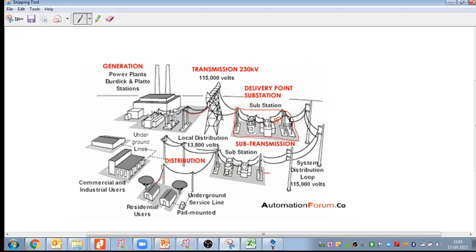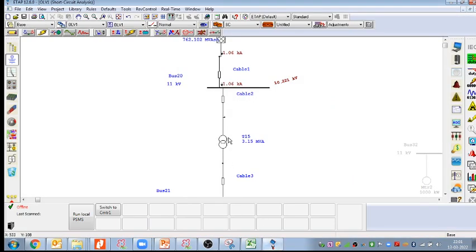Second case that I am taking, if the fault is at this side, then how much fault is fed by these locations to this substation, that we can say remote-in fault. Both are the same, we are telling as the through fault. This is example number one, and this is my example number two right now. And here we have calculated the amount of fault current also. Yes, correct, Siddharth, due to the turns ratio only.